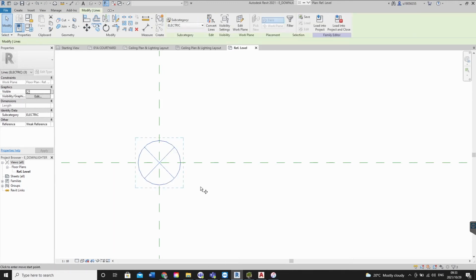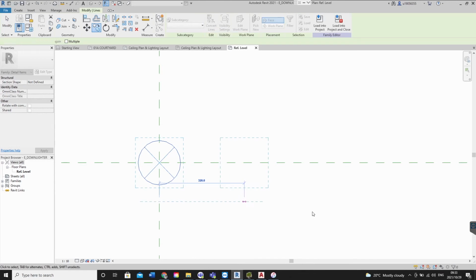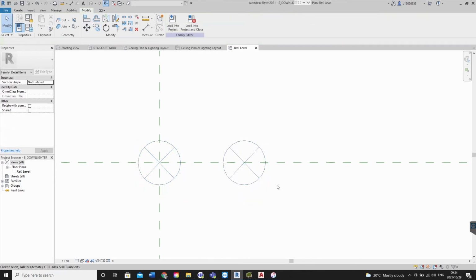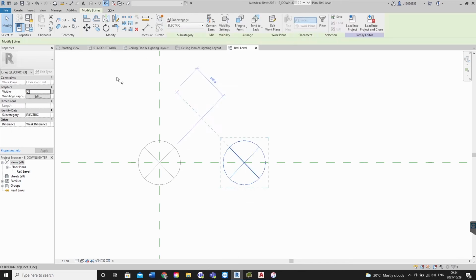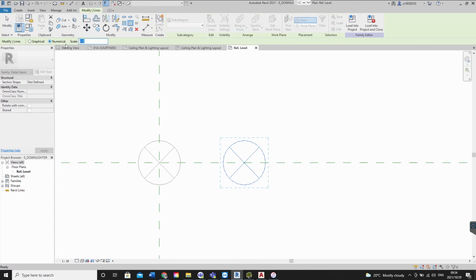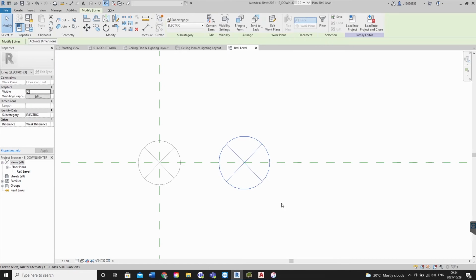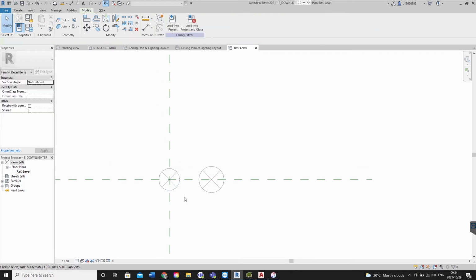So let's copy this. So at scale 1 to 50, you might want to have the slightly bigger just because it might read better. So here I'm just going to go here and I'll go scale, and it's 1.2, 1.2. Okay, so technically this is your 1 to 50, this is 1 to 100. Because a 1 to 100, because the scale's smaller, you might want to reduce the size of these so it doesn't overpower your drawing with these massive symbols. Okay, but your legend will still read the same as long as it ties up with your legend.